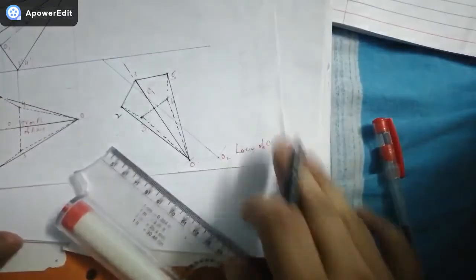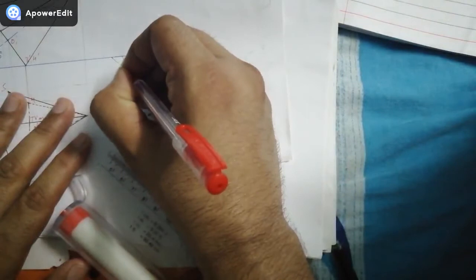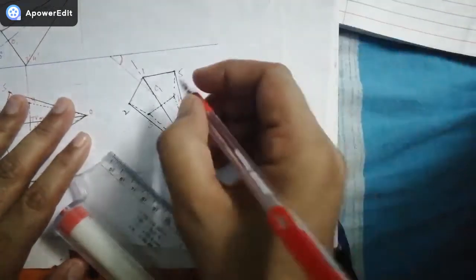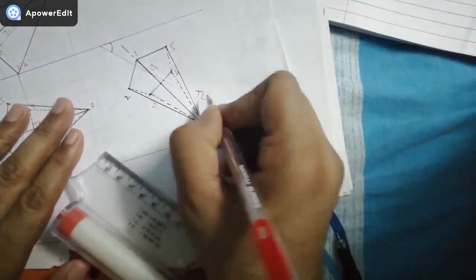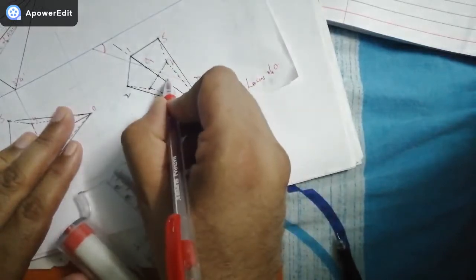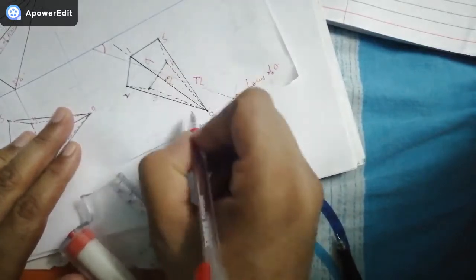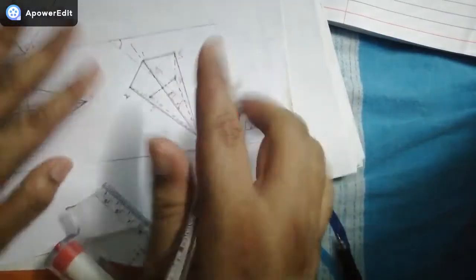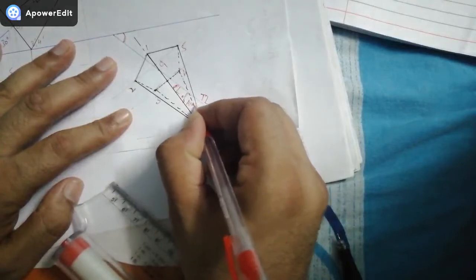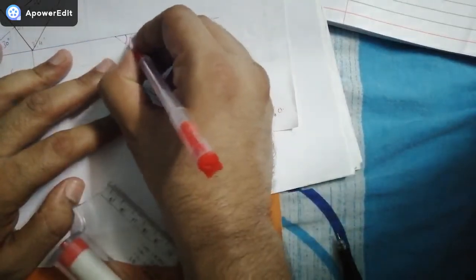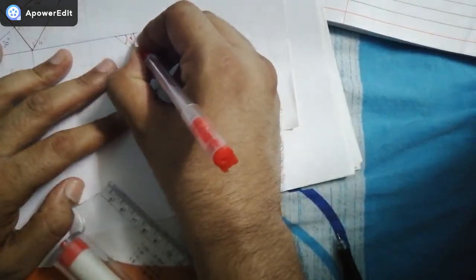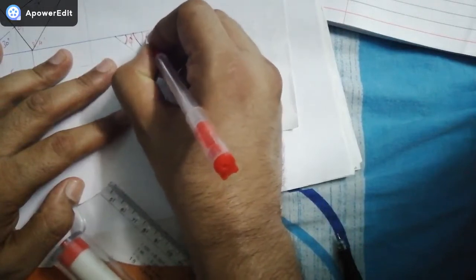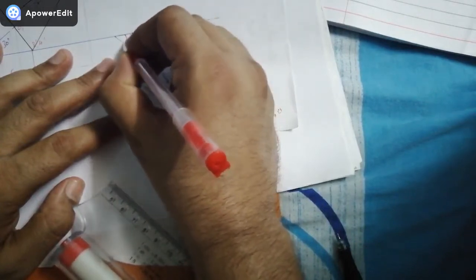Okay, so once I complete this, friends, just for our sake, we will be mentioning this particular true length angle which we have taken earlier. This was the true length, and the other length that we got was the plan length of the axis. So true length of axis we name it, and the other one was plan length of axis, that we are naming now. Okay, now true length was marked at an angle phi, and now if I extend the plan length, this is at an angle of beta. It comes very easily.